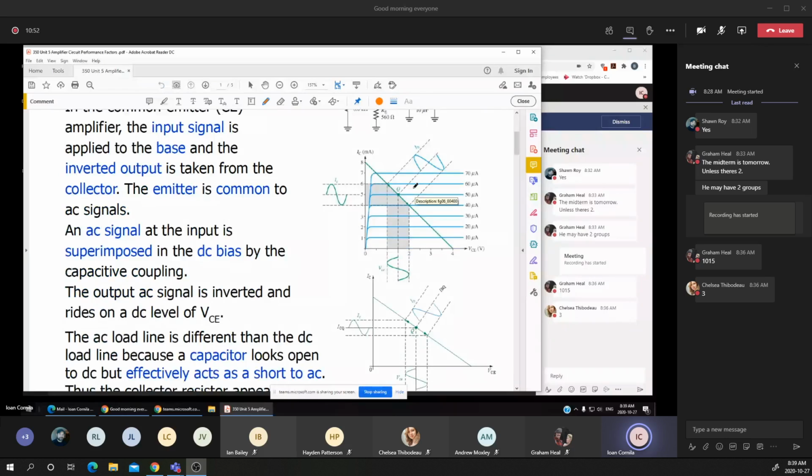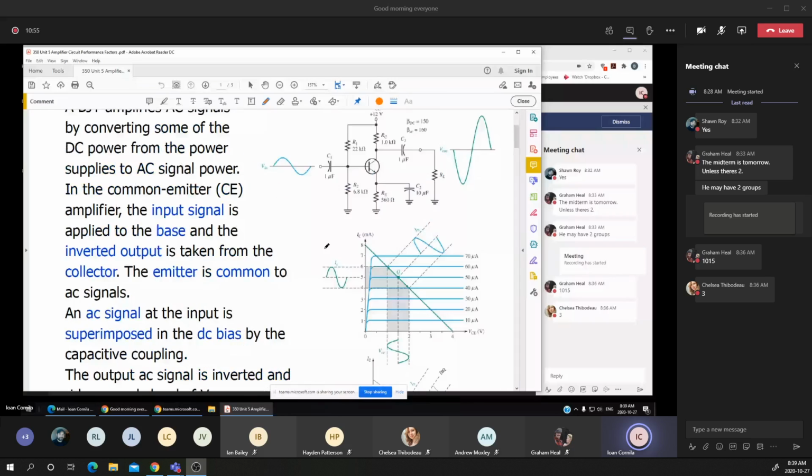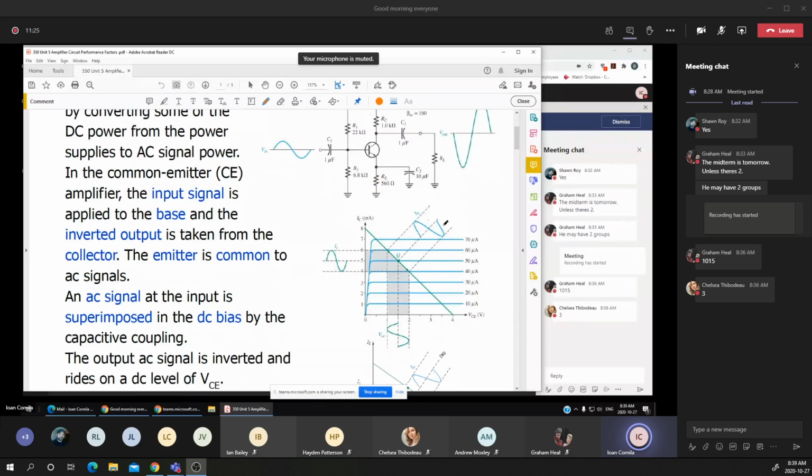Now, once the transistor is placed closer to or in the mid-range of the load line, we can apply an AC input voltage. You notice that the Vin is a small signal in terms of the voltage, or can be expressed in terms of the current. As the voltage is changed, the IB current is changed, which means that we have a swing in the IB value.